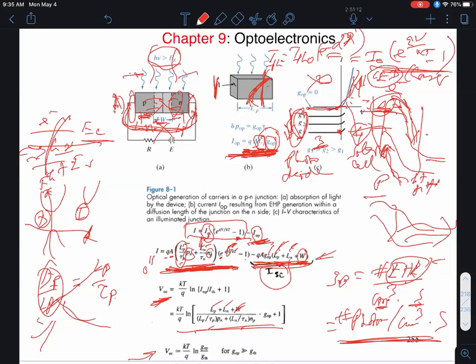So let's pretend that these parameters LN, LP are the same on the two sides, the lifetimes tau N, tau P are the same, and PN, NP are also the same, so comparable dopings, just to get a rough idea. And I've ignored the W, so what do I get? If I made all these highly simplifying assumptions, and furthermore assume a large photon flux, so G optical is very large, I can even ignore the 1 at the end. So this simplifies to this. I basically get G optical divided by everything left over here, and that can be written as G thermal.